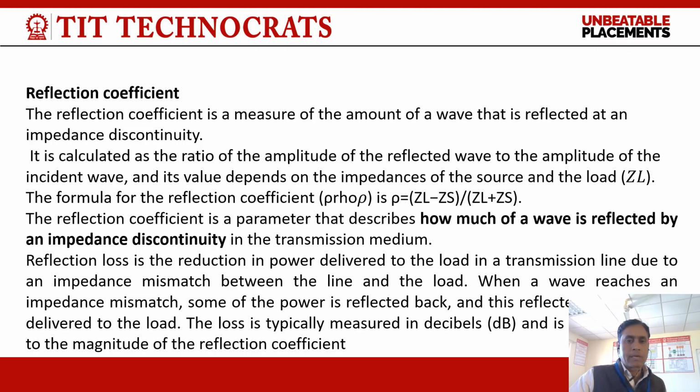Reflection loss is the reduction in power delivered to the load of a transmission line due to an impedance mismatch between the line and load. When a wave reaches an impedance mismatch, some of the power is reflected back, and this reflected wave